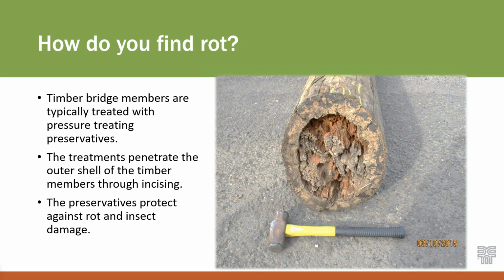So how do you find rot? We talked a little bit about where you look for it. And rot's hard to find. Piles and timber members typically look really good until they've rotted almost completely out.